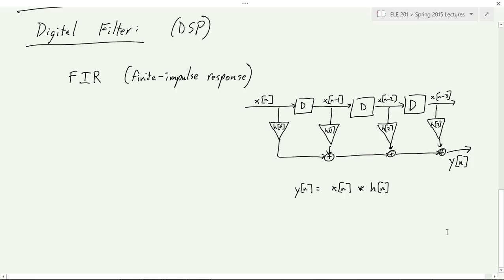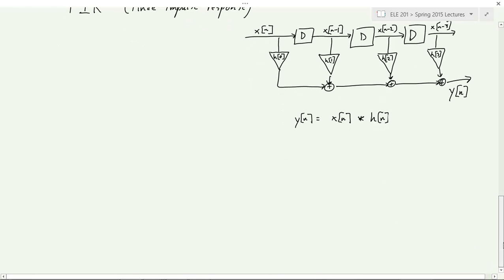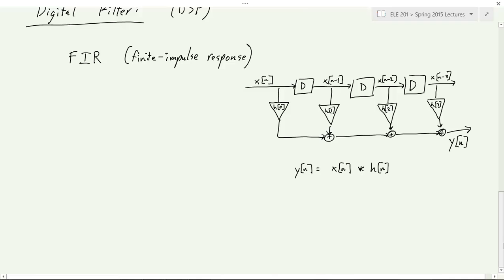Of course, there are other techniques for DSP. Sometimes you would rather use the Fourier transform explicitly to do your convolutions if you have a long enough buffer. But sometimes you do it directly like this if you're doing a short convolution. So what does that mean? In an FIR filter, you have a finite length impulse response, and we would say that the order of this filter is 3. So this is a third order FIR filter.